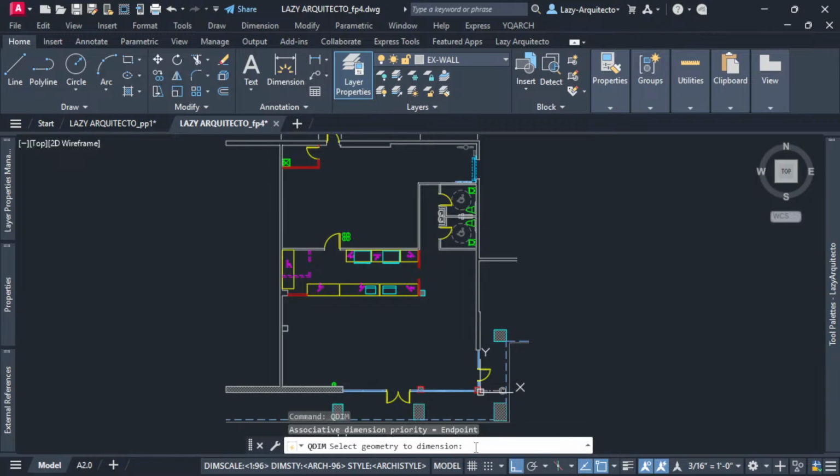But the secret option is right there, and you can access it with the F key on your keyboard. And once you press enter, you can see that we are activating the fence option. Again, it wasn't provided by AutoCAD, which is weird. You'd never know this, but it's there.